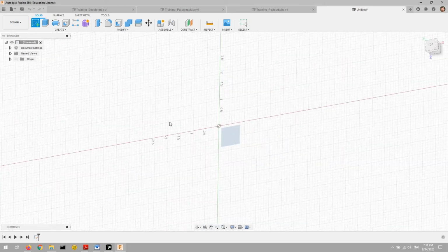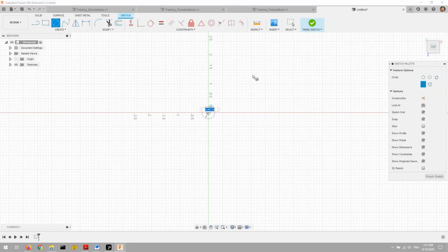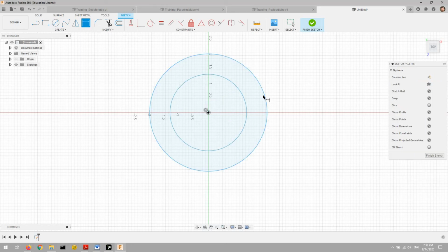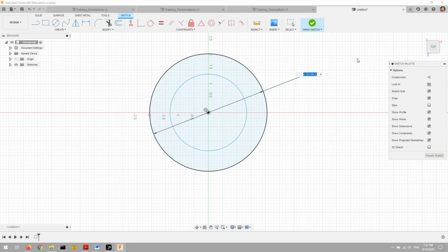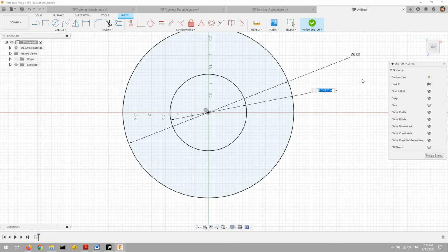And coupler, again, is going to be a simple cylinder. So, couple of circles, define this one to be the inner diameter of the hull, which is 6 inches. And since it's going to be made of the same stuff, the inner diameter is going to be 0.17 inches smaller than the outer diameter.